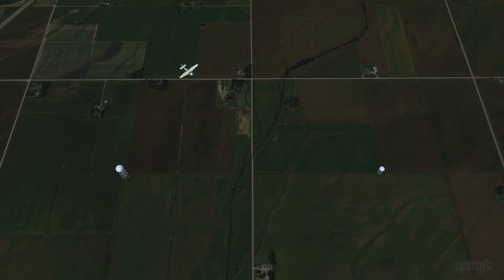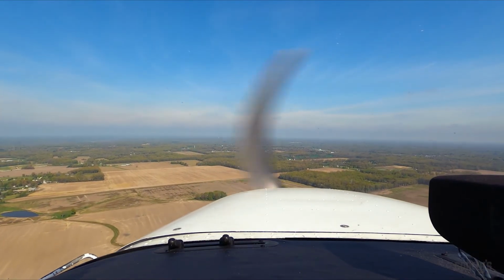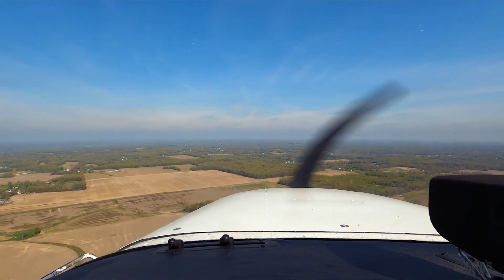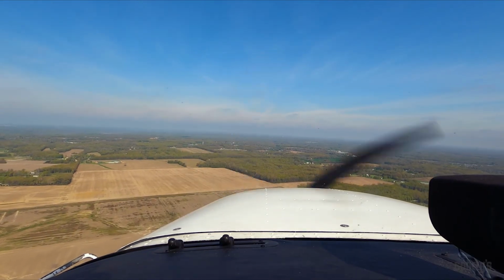The two pylons should also be at the same elevation, since differences of over a few feet necessitate climbing or descending between each turn. The pylons should also rest along a line perpendicular to the direction of the wind. Since you'll be flying the maneuver in close proximity to the ground, identify a field or road nearby to serve as an emergency landing spot.